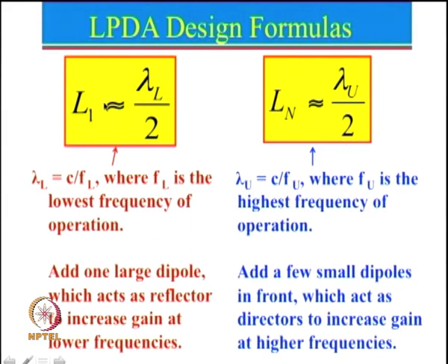Now, you can see here this is written as an approximate, and you might wonder that earlier I had always mentioned to take the dipole dimension as L plus D equal to 0.48 lambda, but here why we have written lambda by 2. First of all it is approximate. Second, this antenna is very broadband, so a small shift in the frequency here and there will not make a difference. However, this is an additional thing which I want you to really keep in mind when you are designing a log periodic dipole antenna.